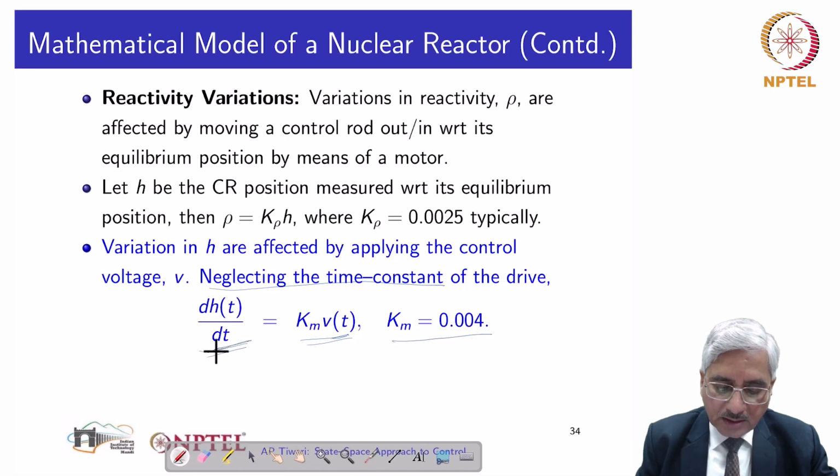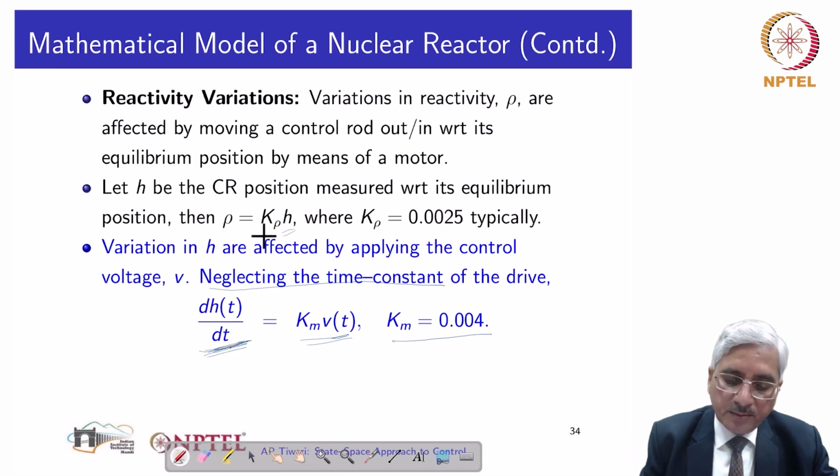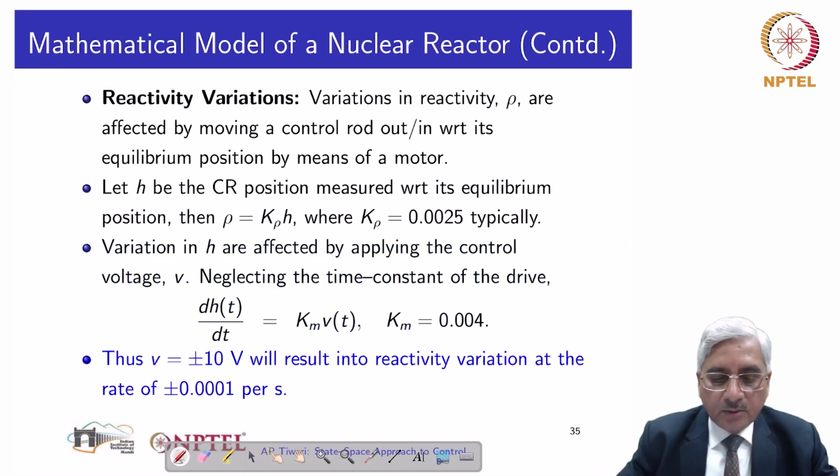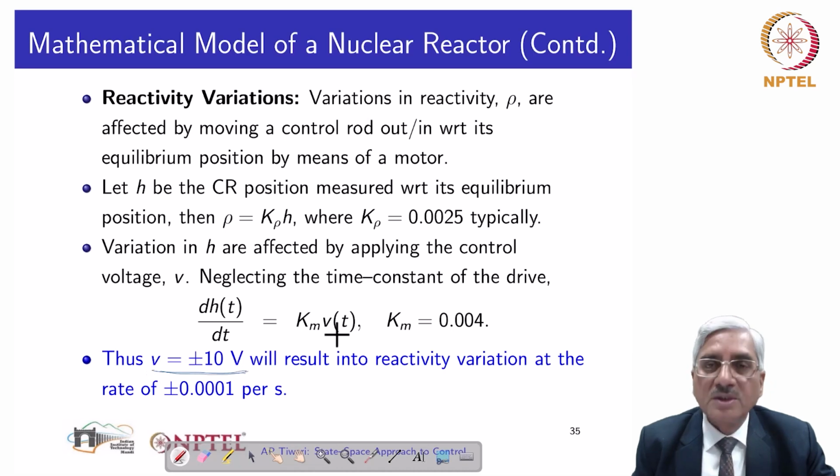So this is essentially the control rod speed, and its integration is the control rod position, and that multiplied with k rho will give the reactivity at any time. So we can make use of this expression. And of course, all these voltages, this is the input voltage to control rod. Similarly, the output of the linear amplifier and that rate amplifier or differentiator are generally in the range of plus minus 10 volt for rate, but for linear amplifier 0 to 10 volt.